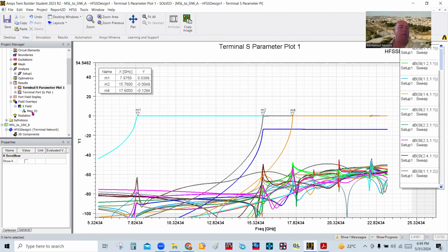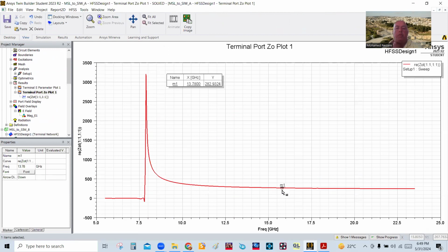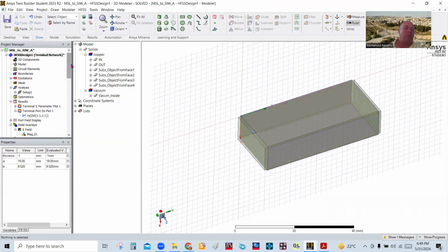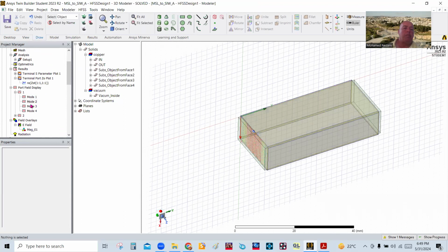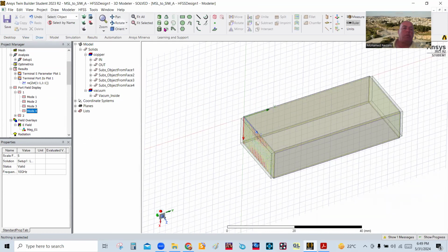The thing that you really want to do, and of course, let's look at the impedance. The impedance around this area is always about 200 and more than 250 ohms. One thing we would want to make sure of, and this is good for people first exposed to waveguides, is that here's the input port, and you have to set up the number of modes.